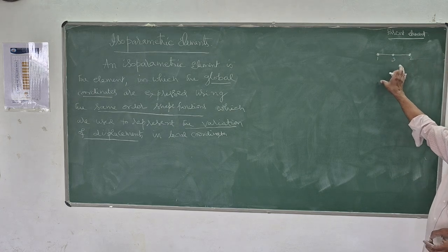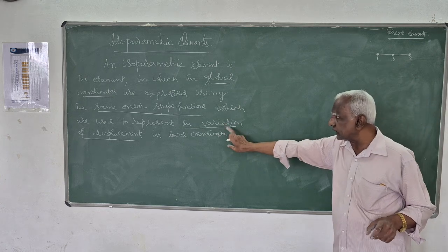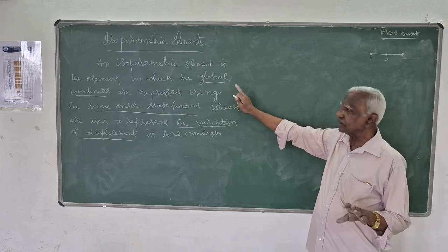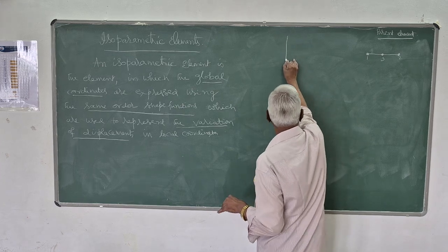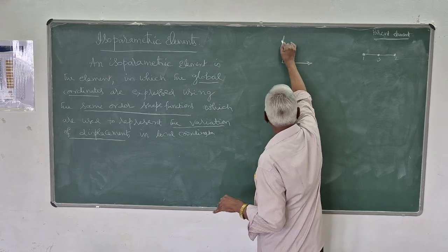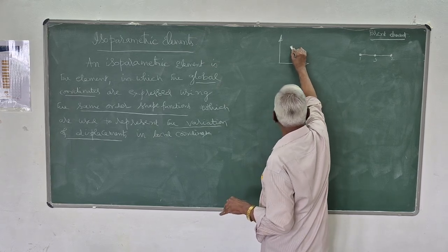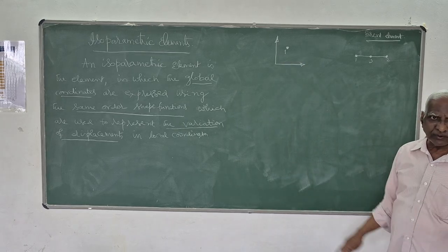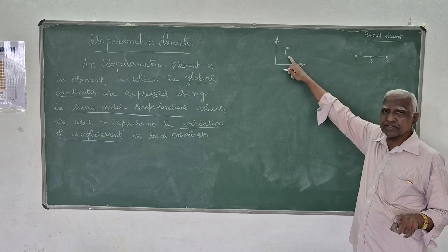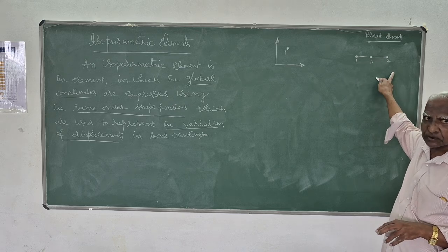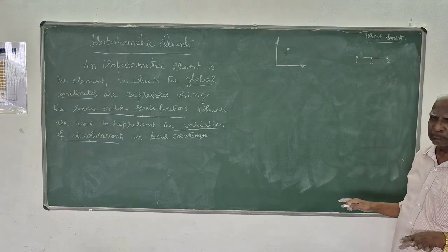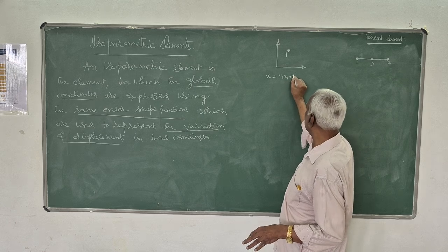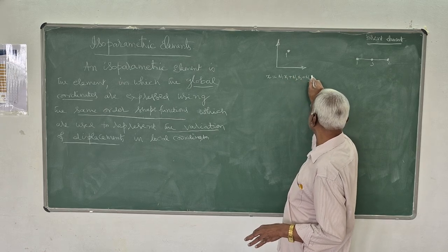That same shape function which you have derived for representing the variation of displacement, if you use it for global coordinates, the representation of the coordinate of node 1, x1, the nodal coordinate, then x is equal to N1 x1 plus N2 x2 plus N3 x3.